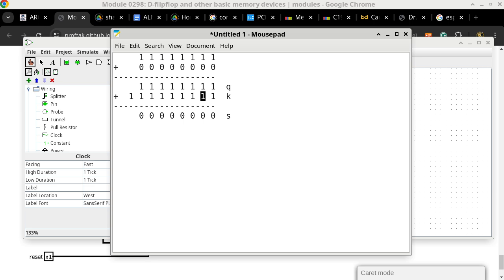You can control where it starts the countdown, and when it counts down to 0, it will cause what we call an interrupt, where the operating system has a chance to go like, oh, I see that 15 milliseconds has passed. Let me see what I need to do. The first thing is to hit the watchdog so that the watchdog does not time out and start to reset the whole system. And then plus a whole bunch of things like keeping track of the real time and whatnot.